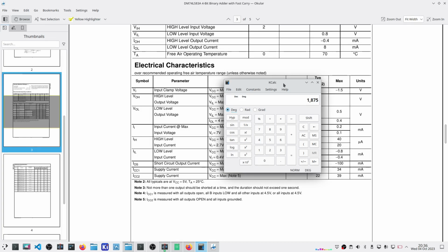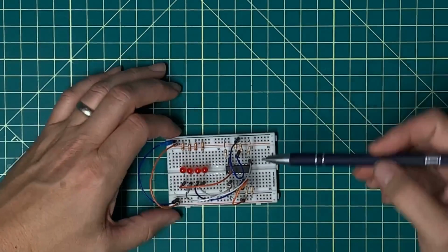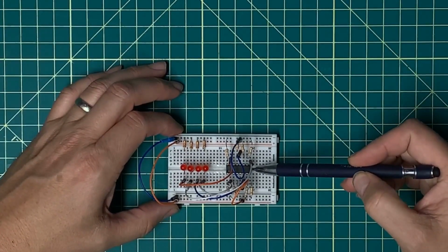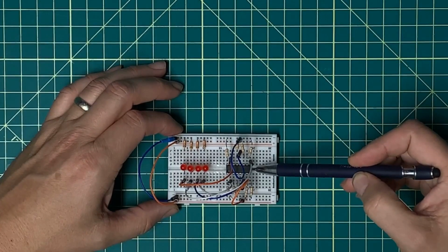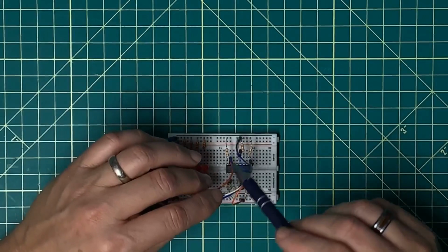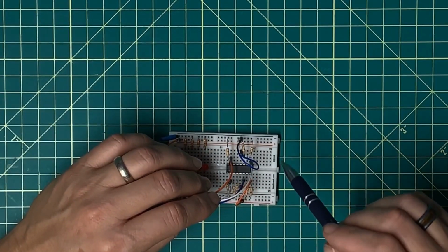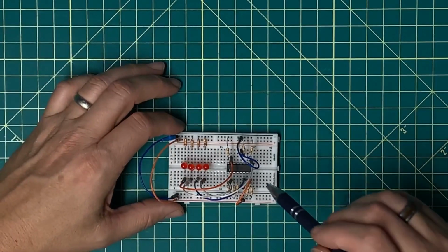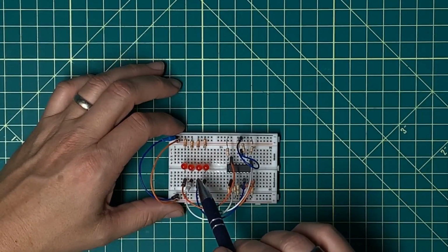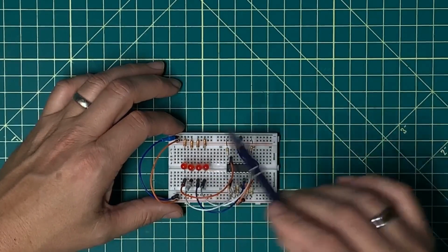Well, let me show you what I built. It's rare when I get to zoom down like this anymore. So this is a single 74LS83 IC. This is the 4-bit adder I've used in the build for now. And what I've done is I've just tied things up similar to what I have in the ALU Adder, with the outputs coming over here to the LEDs tied by 1K resistors to ground so that I can see the